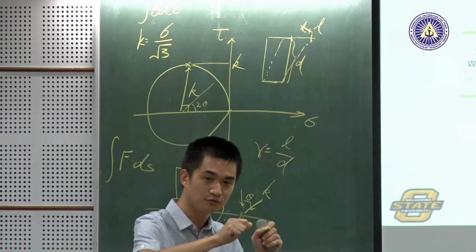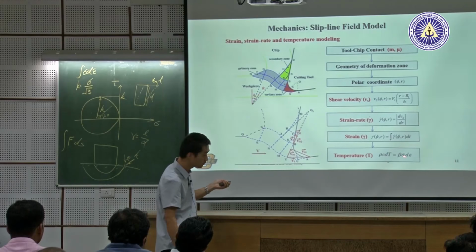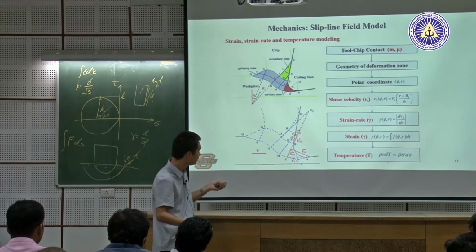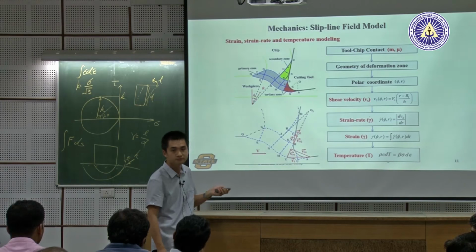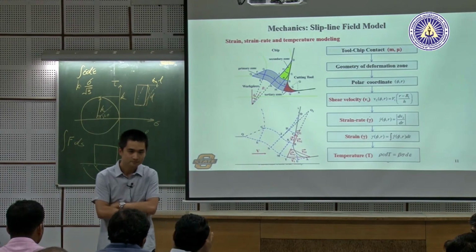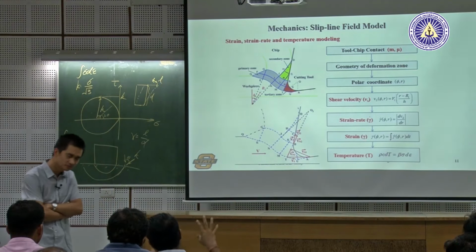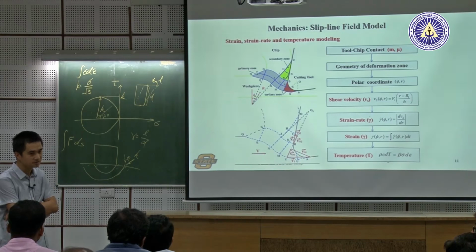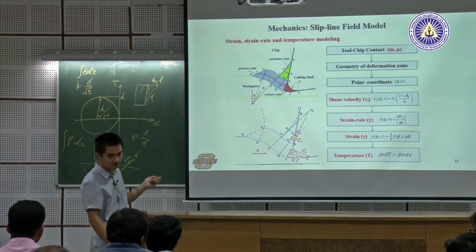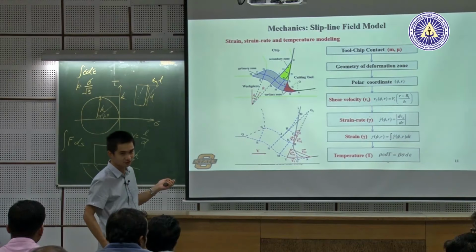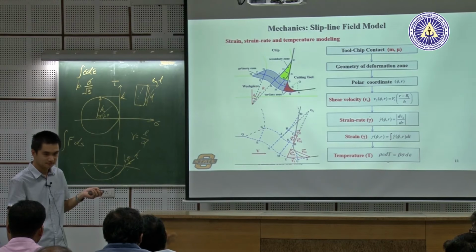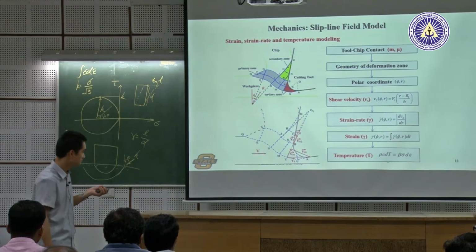But there will be conduction also, right? So how do you account for that? For this case, we don't consider it directly; that's why we add beta, and we use 0.7. I know there's an assumption. If you assume it to be adiabatic, I can agree with you. Yeah, some sort of adiabatic. The purpose is we're trying to develop an analytical model for this, so there are certain assumptions. For some materials, it's actually fairly accurate. If you're talking about nickel or titanium, I think it would be fairly accurate. That's a good point.